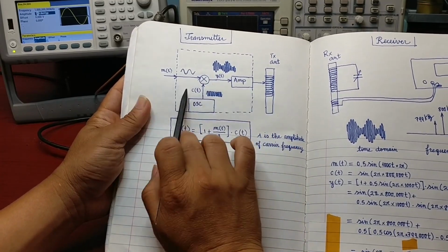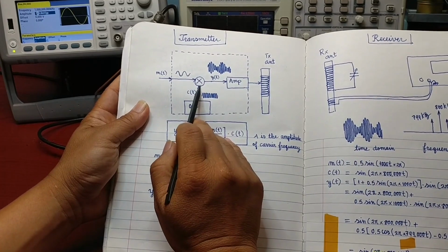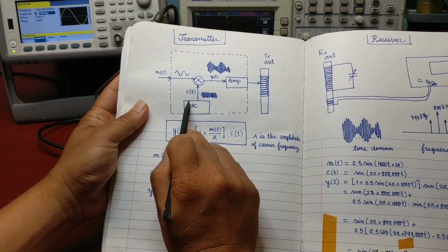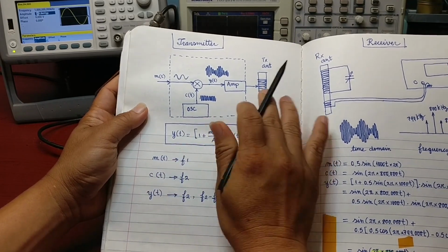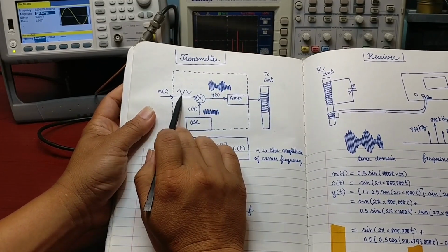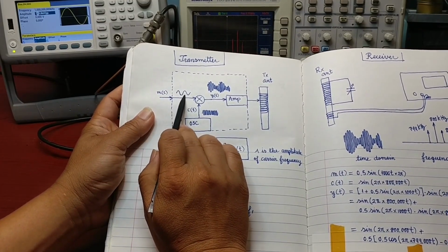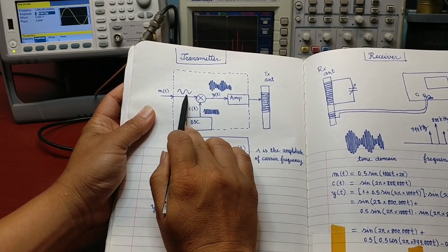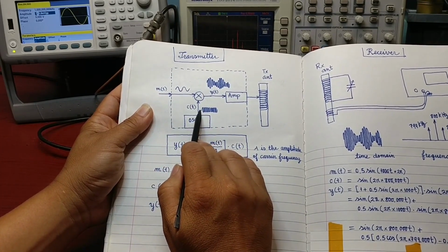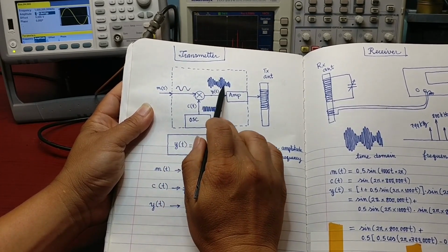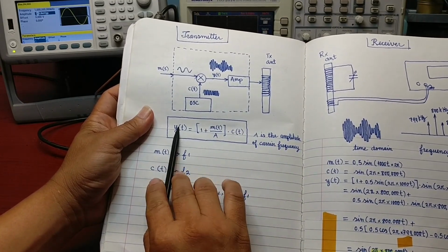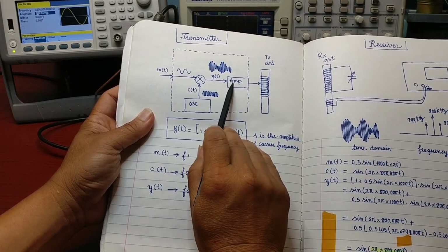here is the block diagram of the AM transmitter. This is the modulator or the mixer. This is the local oscillator, generating the carrier frequency. Our carrier frequency now is 800 kHz. This is the modulating signal input. The modulating signal is now a 1 kHz sine wave. When the modulating signal and carrier frequency signal are mixed, it will produce the AM signal output. Here is the formula of the mixer or modulator of the AM signal. The AM output signal is then amplified and transmitted via the antenna.